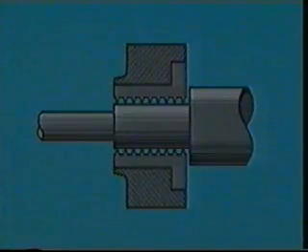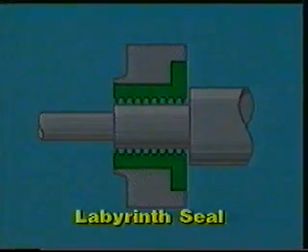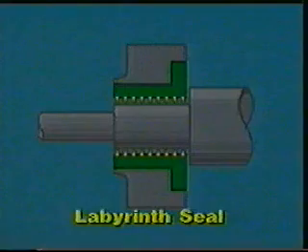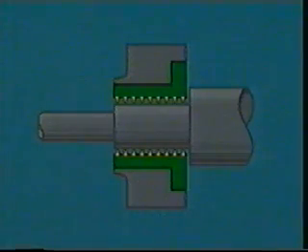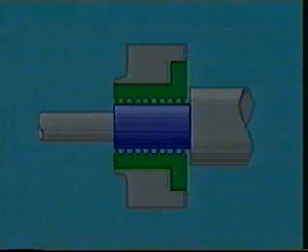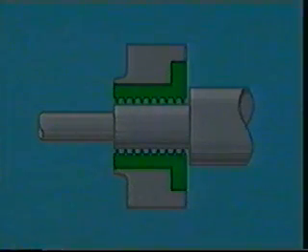The simplest type of seal is the labyrinth seal. It has a series of grooves machined to sharp knife-edge thickness that maintain a close clearance to the mating part. It can either be stationary or rotating. The mating parts are made of a softer material such as babbitt, so they will wear before the labyrinth does. Labyrinth seals can be found in multiple, stepped, and interlocking configurations. Sometimes carbon rings are included with the labyrinth seal.